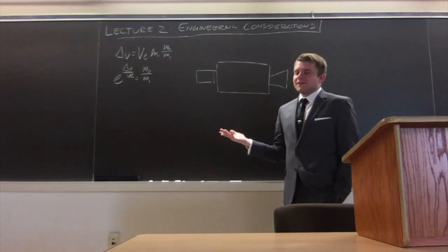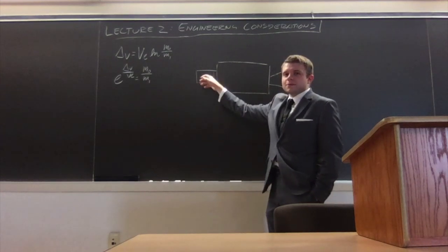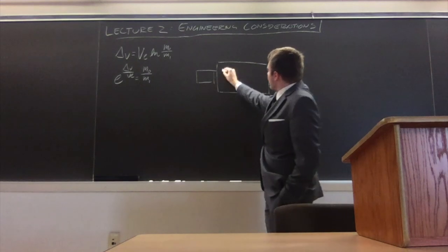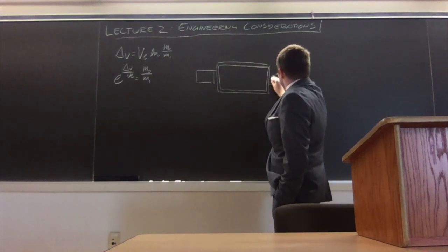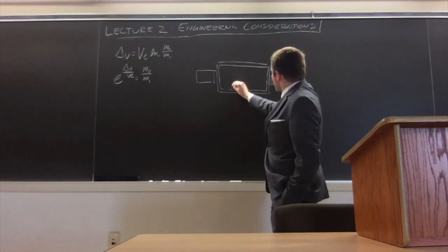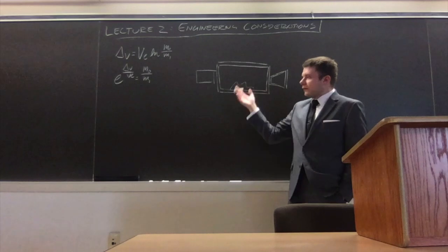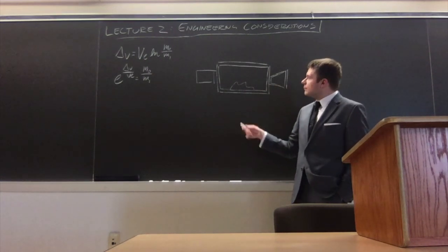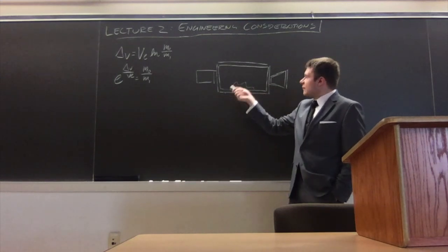The problem is that the final total mass of your rocket isn't just the mass of your payload, which is what some people who first look at this may originally interpret it as. Your final total mass is the payload plus the mass of your tankage plus the mass of your engine and whatever propellant residuals you may have in your propellant tanks. These are all real-world considerations that you have to make when you're trying to design a rocket of any kind, because, well, you need something to store your propellant in, and you can't burn all of your propellant.